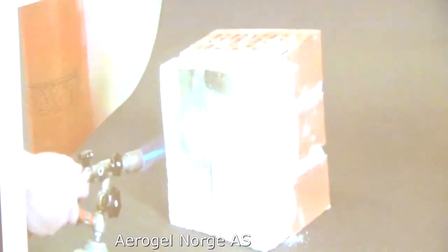Another important property is the reaction to fire. This is a small test at EMPA. This is a brick with 5 centimeters of aerogel render, and on the left side this is the pure aerogel render, and on the right side this is with the reinforcement render and the final render, the same as in the old mill. Yes, and nothing happened, so you can see it here. It's 1,500, 600 degrees hot, and nothing happened, no smoke.